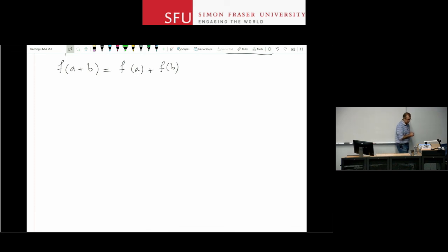So this is a very, very simple example. You only use superposition for linear circuits. You should have seen this in your electric circuit theory. If you need a refresher, just go and do a quick practice on that. And these techniques that I talked about are the tools that we need all the time in electronic circuits. You use KVLs and KCLs all the time. You use superposition from time to time. Norton and Thevenin equivalent circuits are used all the time in electronic circuit analysis.